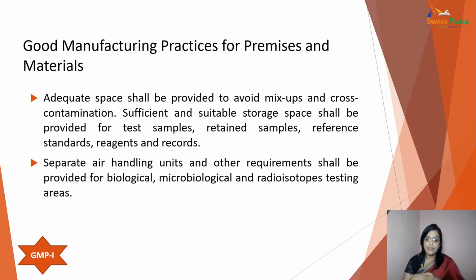The design of a laboratory shall take into account the suitability of construction material and ventilation. So separate air handling units and other requirements shall be provided for biological, microbiological and for radioisotope testing area.